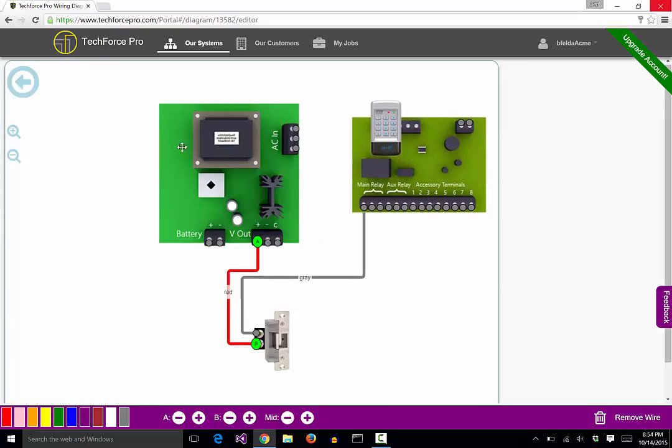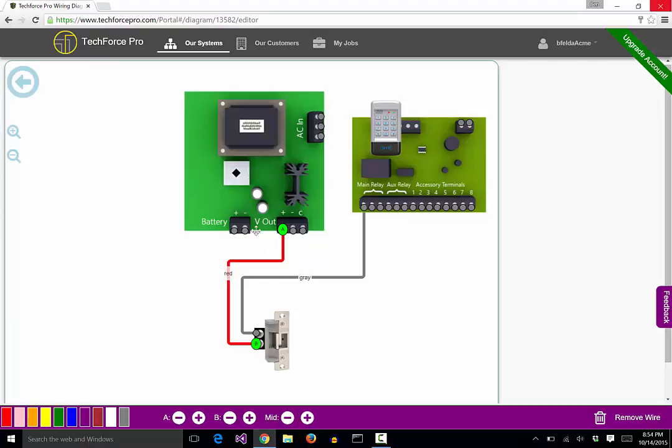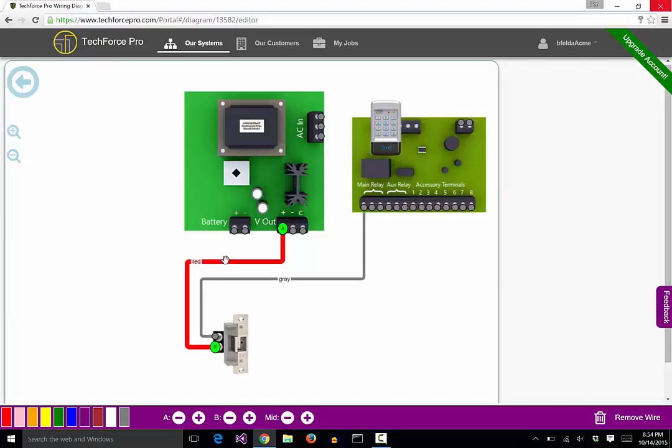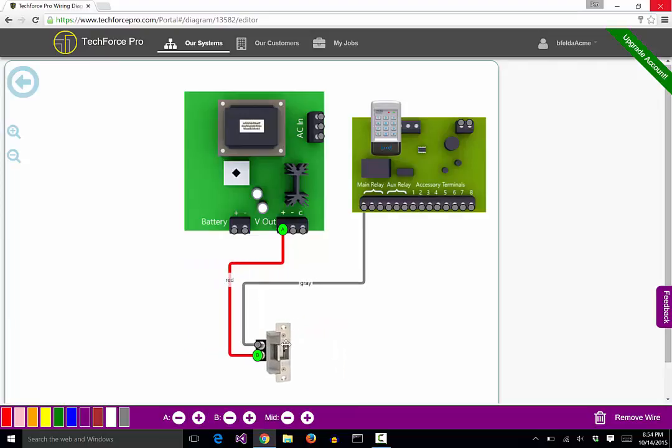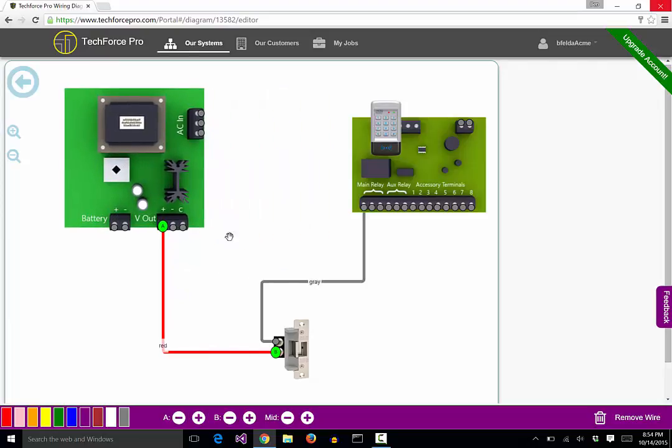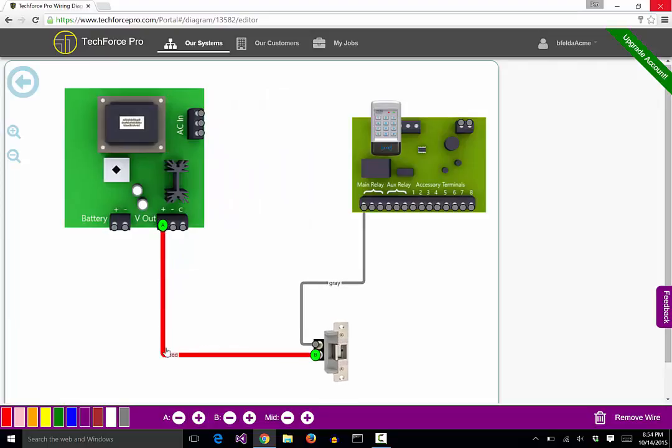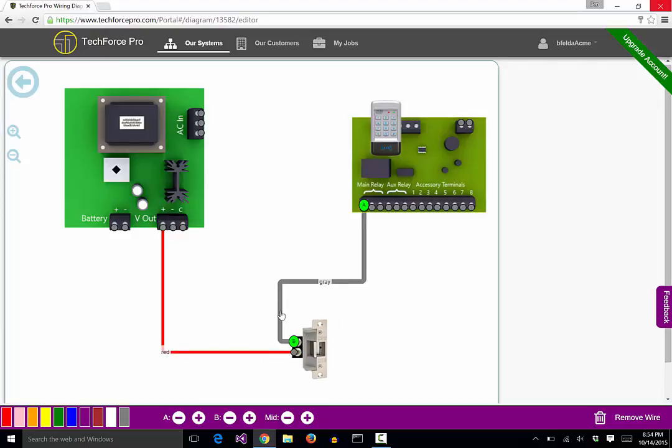So once you get the hang of starting to wire these up, you'll see the advantages of doing it this way. There are other programs like Visio where you can drag connections to other parts, and you can kind of drag wires around. The downside of dragging wires around is they don't stay when you move the parts around then. So what you can do is you can first drag your wires to where they need to be, and then just start manipulating the wires, moving the parts to make it look like how you want it to look. Now again, if a wire is just going down and over, there's not much you can do. It's when the wire starts to form this S shape that you can move the middle where it cuts over.